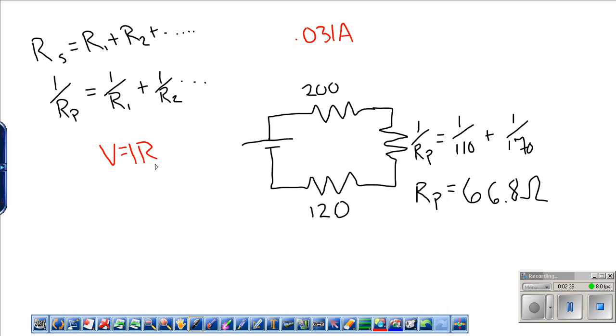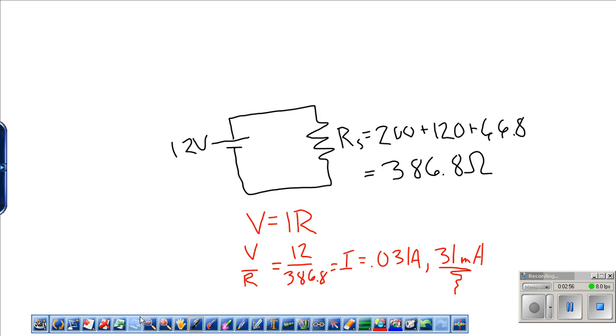Here in this picture, we have 3 resistances, and we have the same current for every single one. So current, I, times resistance, will equal voltage. Now we can find what's called the voltage drop across each resistor. For the last slide, where we had the 12 volt and the 386.8 ohm resistor, it's kind of the trivial case, and we had a 12 volt drop across that one last resistor.